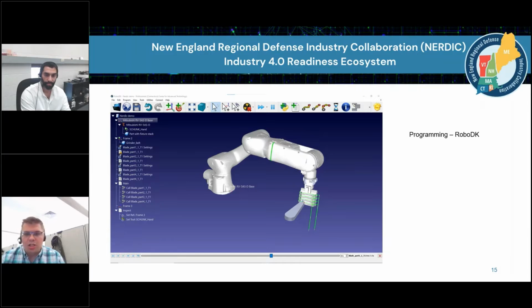And this tool essentially lets me program that way without trying to teach all the points manually and drive the robot around with a teach pendant, or by grabbing it and dragging it as you do with a cobot to try to generate this complex task. And it really frees up a lot of time and energy when it comes to programming, to be able to use standard workflows that you're probably using already in industrial environments.